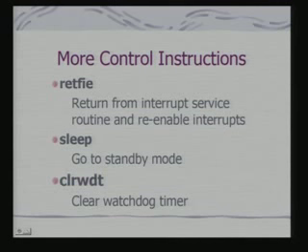Effectively nothing, because in both cases you need to get the return address from the stack. In case of PIC, you have a hardware stack, so the return address is stored in the hardware stack and you have to get it from there. But this instruction typically re-enables the interrupts.